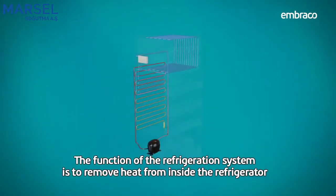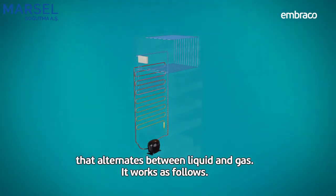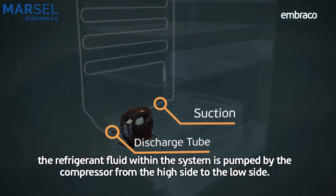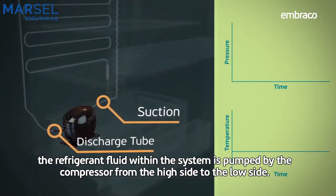The function of the refrigeration system is to remove heat from inside the refrigerator and deliver it outside the space through the refrigerant's phase change that alternates between liquid and gas. It works as follows. When the refrigerator is turned on for the first time, the refrigerant fluid within the system is pumped by the compressor from the high side to the low side.